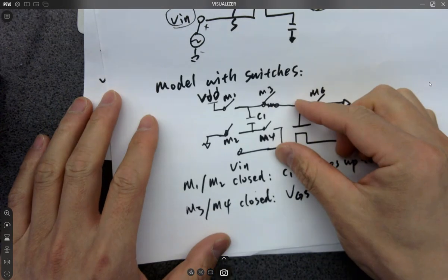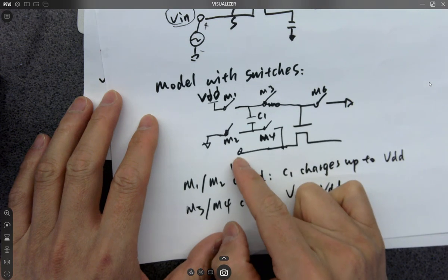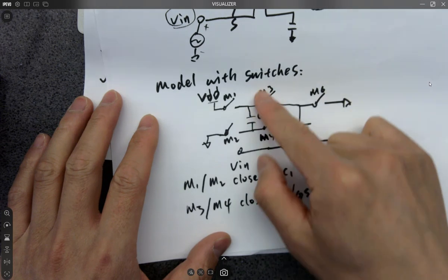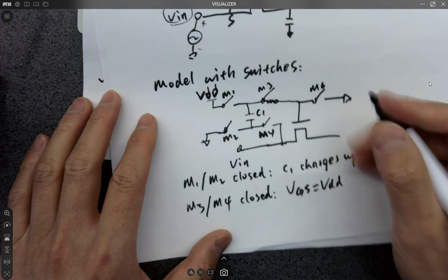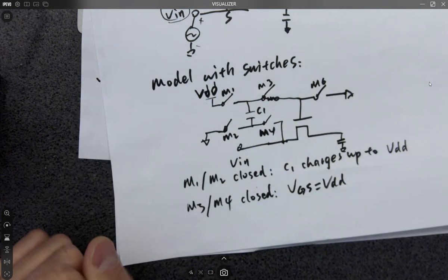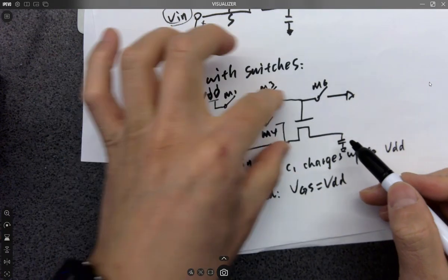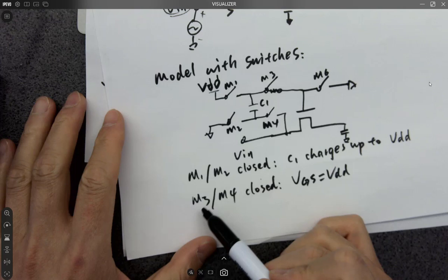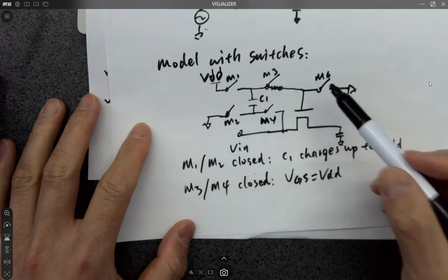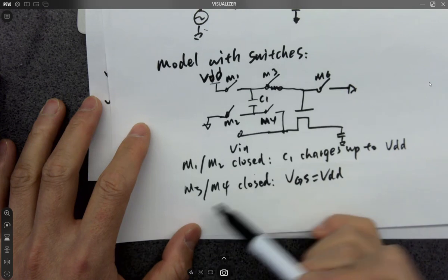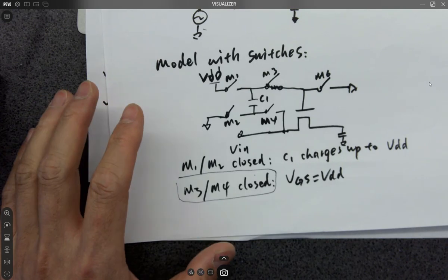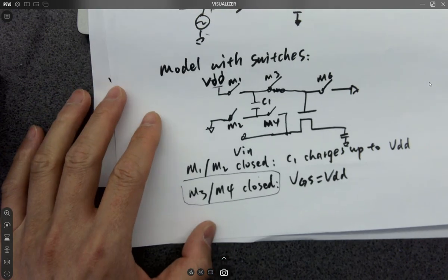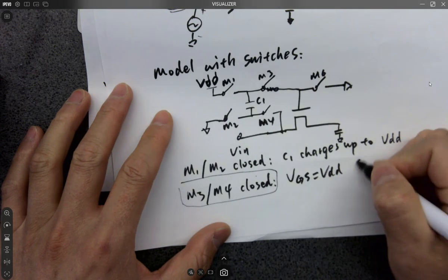So whenever I have a VDD across it, you are ready to do what? Signal comes in, it's adding to this VDD, and it's not changing the VGS over here. So it's actually sampling, right? Sampling. So signal passes through it. During this period, do we want to keep M6 open or closed? M6 should be open or closed? Open. Why?